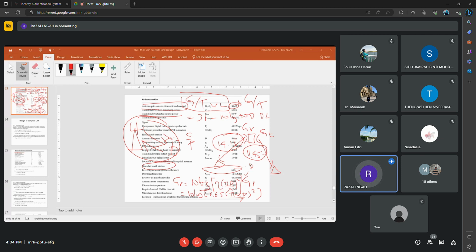So you might ask, can't we increase GR here, right? But it depends on the signal. If the signal received at the receiving antenna is lower than the sensitivity, then it doesn't matter how high a gain you use for the receiving station.